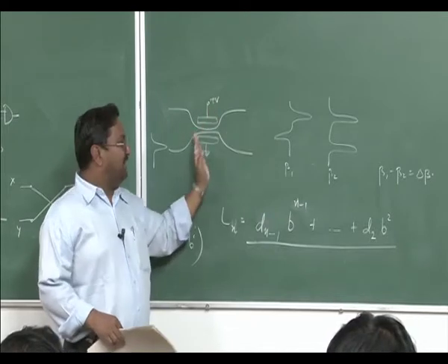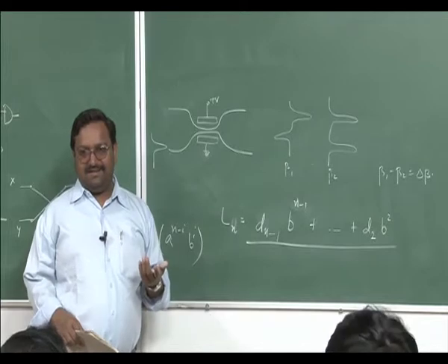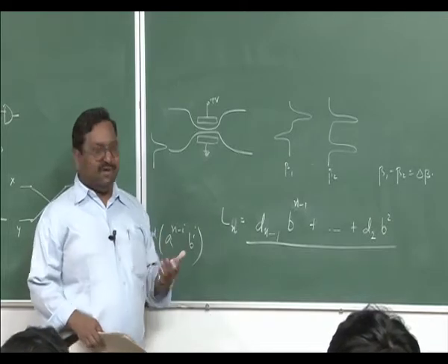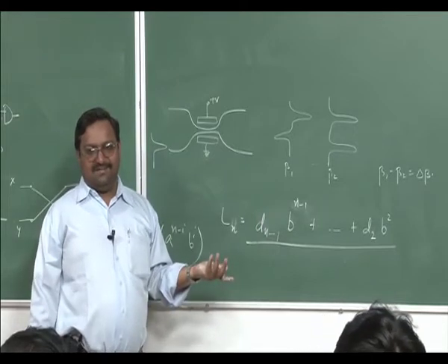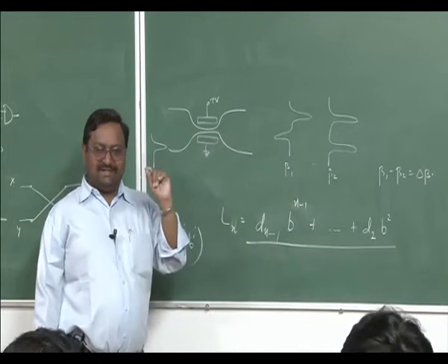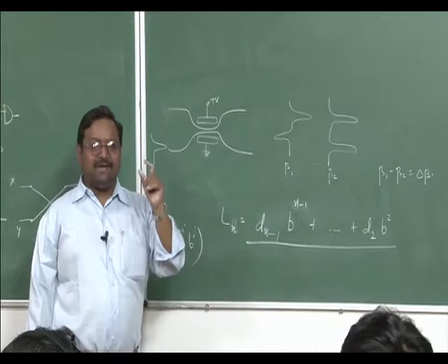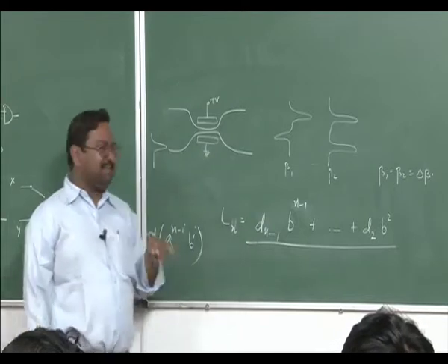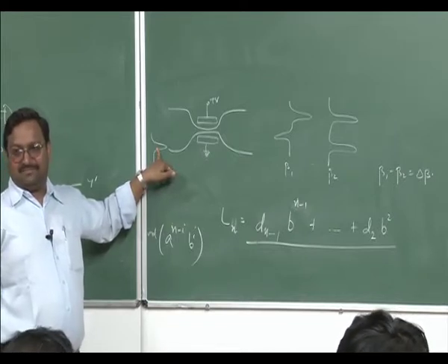If you change your voltage, so that delta beta times length becomes 2 pi or an integral multiple of 2 pi, power will remain in the same fiber. One important thing: going from cross to bar state may take a few milliseconds. But this time does not decide the bit rate which can be injected into the system, because this is not changing the state of the system.